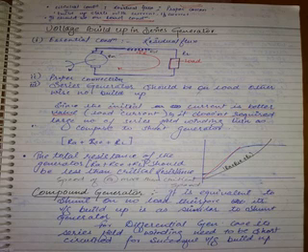The total resistance of the circuit should be less than the critical resistance. Right, like this: RA plus RSE plus RL should be less than it. You can't divide now.